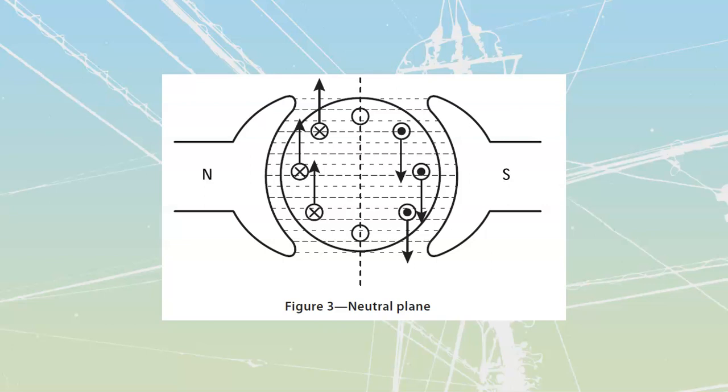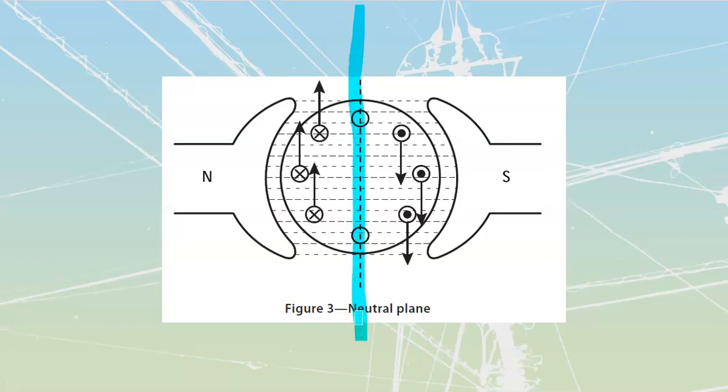And now we are going to establish a direction of rotation. Let's start with our field. We're going to examine this thing only at one side at a time. So we're going to start with the left-hand side. On the left-hand side, I see that I have got my field traveling through from there, traveling through there, etc. So that's going to be my magnetic field, my first finger. I'm going to have my center finger, which shows me I've got current traveling into the page on all of those.